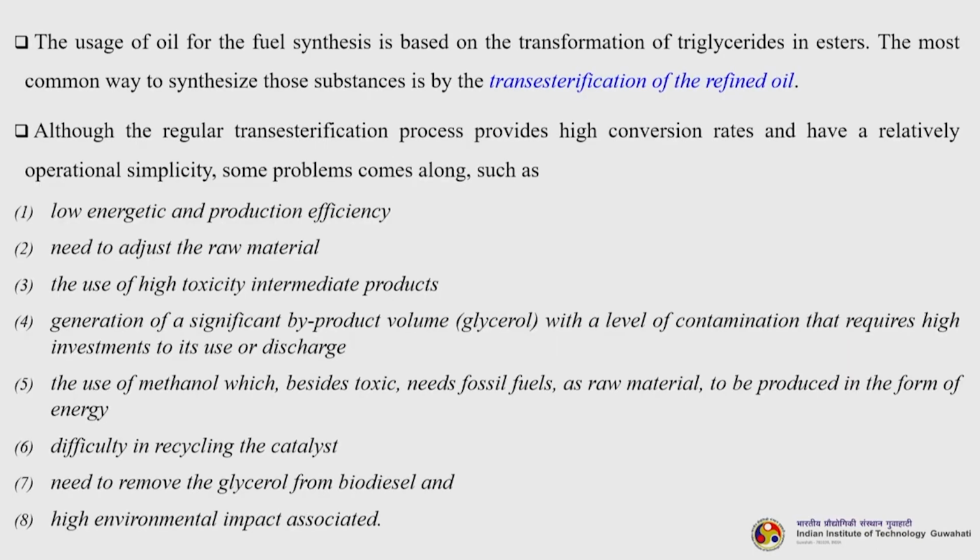So, the use of oil for fuel synthesis is based on the transformation of triglycerides into esters. The most common way to synthesize those substances is by the transesterification of the refined oil. Although the regular transesterification process provides high conversion rates and has relatively simple operation, some problems come along, such as low energetic and production efficiency, the need to adjust the raw material, and the usage of highly toxic intermediate products, a very big problem. Then the generation of a significant byproduct volume, as for example glycerol, with a level of contamination that requires high investment for its use or discharge.